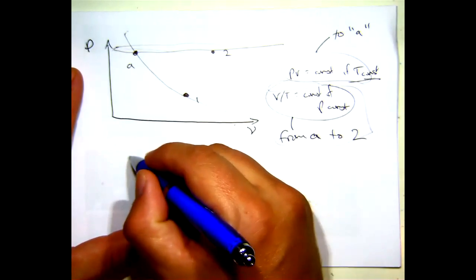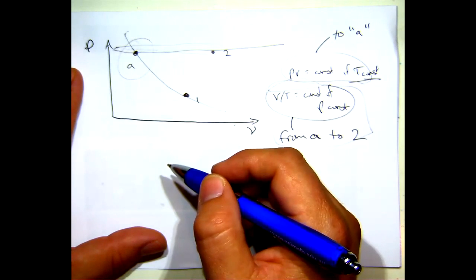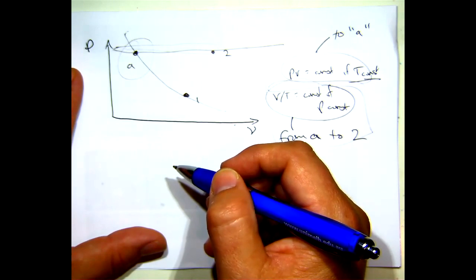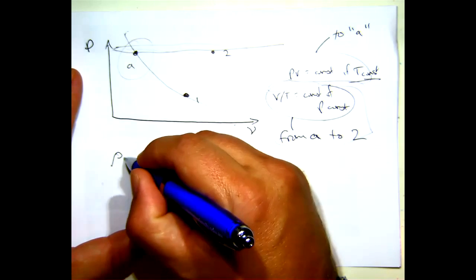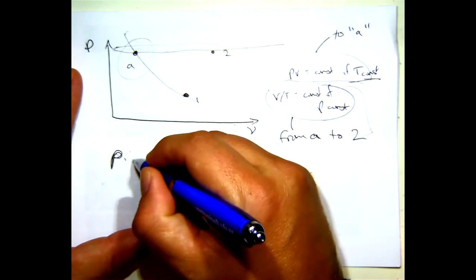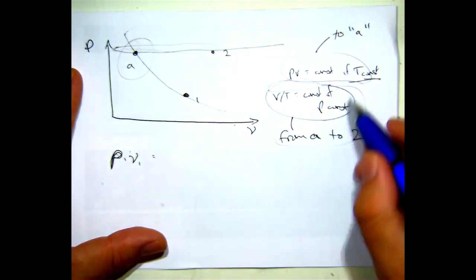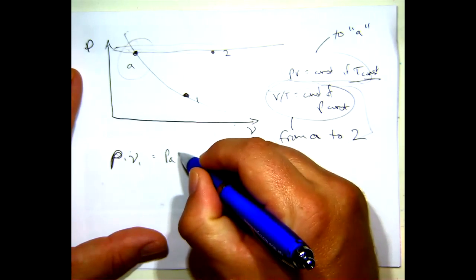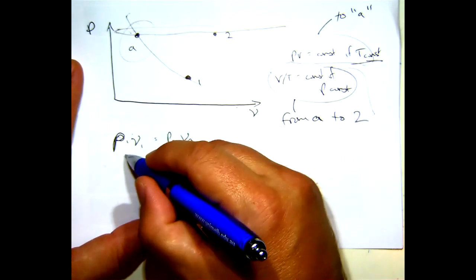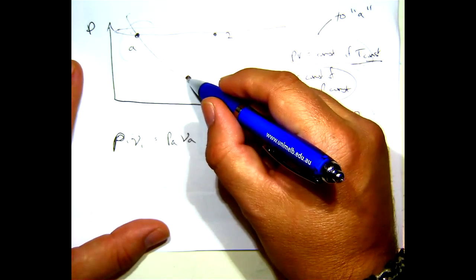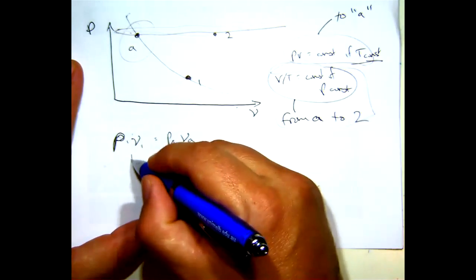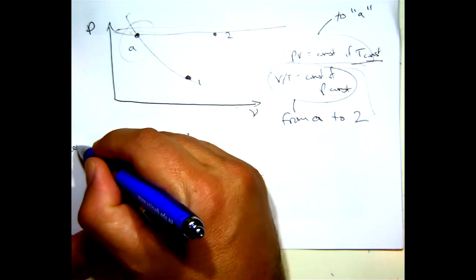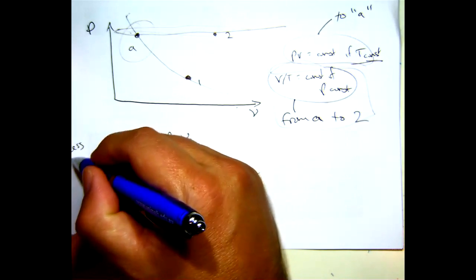The first one says, so I want to make a point that this location makes no difference, which is just some mathematical crossing stuff out. So we've got pressure 1, specific volume 1. If it's a constant, that means it's the same here as it is here. So P1 V1 equals PA VA. I've got the temperature here is the same as the temperature here. TA equals T1. That's all good. That's for process 1. Process whatever. Process big A.